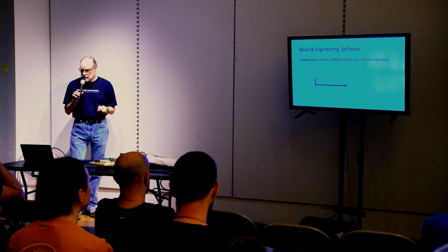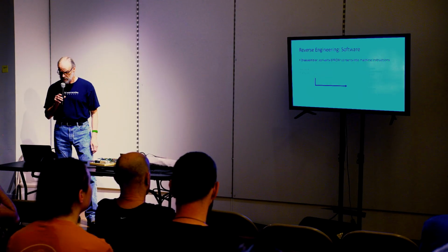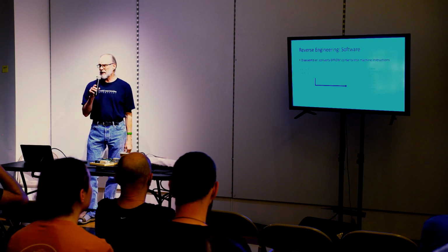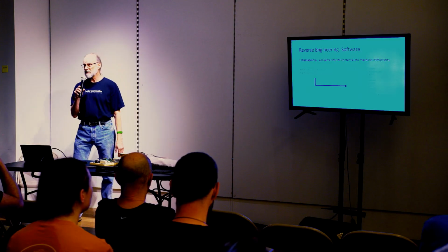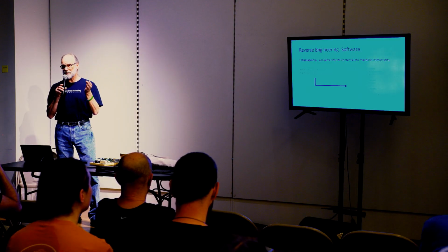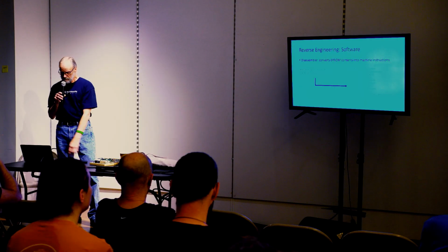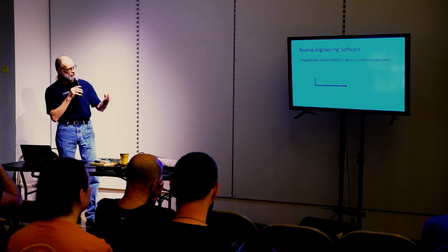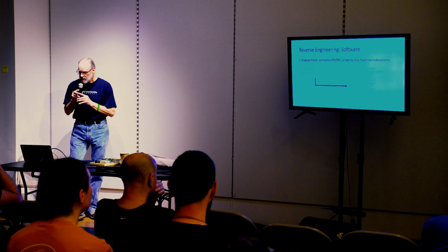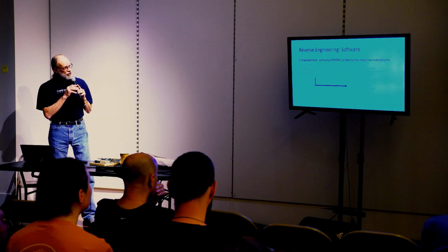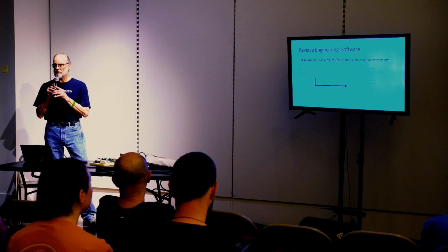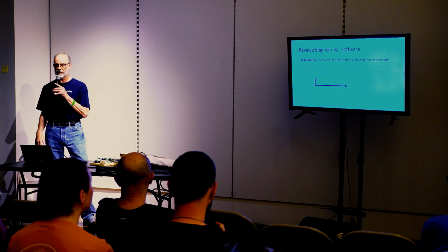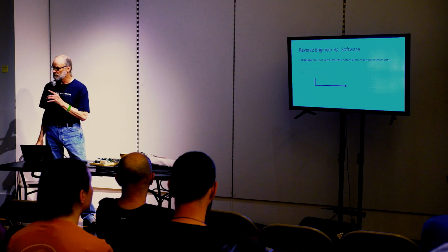And then, of course, everyone's favorite, you have to reverse engineer the software. This was long before they had programs like Ghidra that help you out with a lot of this stuff. This was just a pure disassembler that dumped the code into a basically impenetrable wad of machine instructions, like you can see on the right. If you care, that wad of machine instructions on the right is actually checking to see if the engine is going too fast, and if it is, it cuts off the spark and the fuel so that you don't blow the engine up.